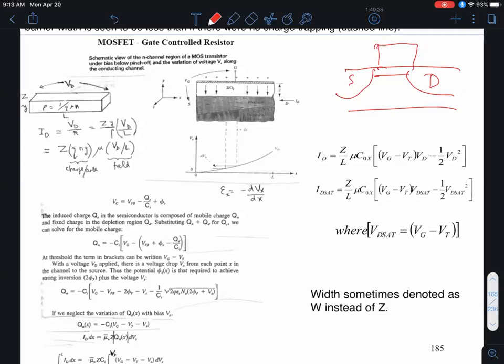So when you send ICs into outer space, they're designed specially, and those are known as rad-hard devices, meaning that they're hardened against radiation, such as cosmic rays, and in the process they're also hardened against damage due to, say, time-dependent dielectric breakdown and other kinds of damage that I'll discuss maybe on Wednesday. Okay, it's an important question.